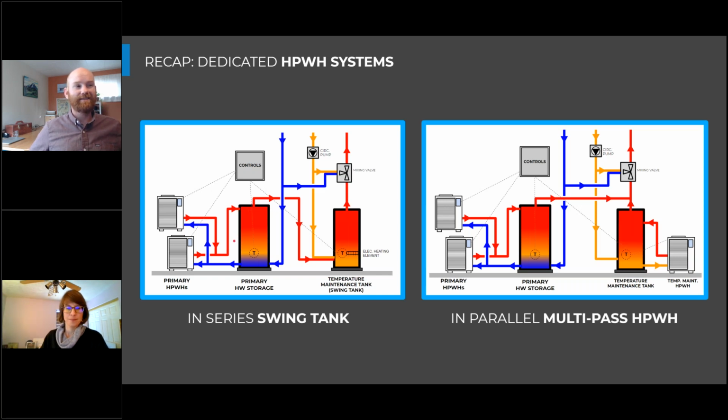So typically with single pass heat pumps, multiple storage tanks are connected in series, and they can be connected in parallel, but you often get a little bit better use out of your tanks if they're connected in series, and the control is slightly simpler if they're in series. And then with multi-pass heat pumps, there is likely reason to connect those in parallel if you have multiple tanks. All right. No other questions.